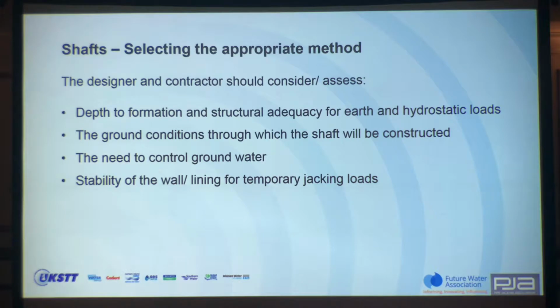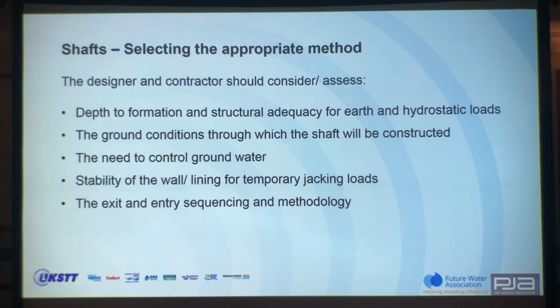In all of this, as I mentioned, and we've just had the presentations that talked about the temporary jacking load. So when you've got the rig in the bottom of the pit or the shaft, and you're going to push forward, you put in a load which will effectively go onto the back wall. Again, I'm going to touch on that later. There is normally, or hopefully, ground behind the shaft that's taking it out, but the lining still does have to do some work. I touched on it briefly. So the method of exit and entry, the sequencing and the methodology needs to be thought about.